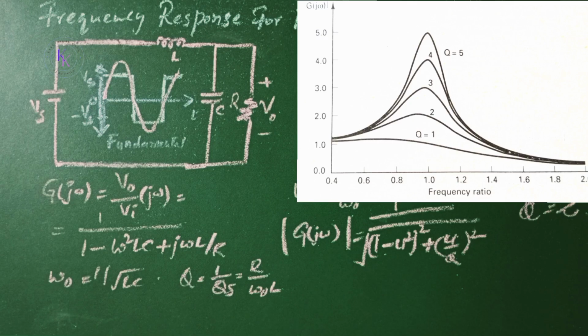If the capacitor is shorted due to a fault in the load, the current is limited by the inductor L. This type of inverter is naturally short circuit proof and desirable for applications with severe short circuit requirements. This inverter is mostly used in low voltage, high current applications where the input voltage range is relatively narrow, typically up to plus or minus 15%.